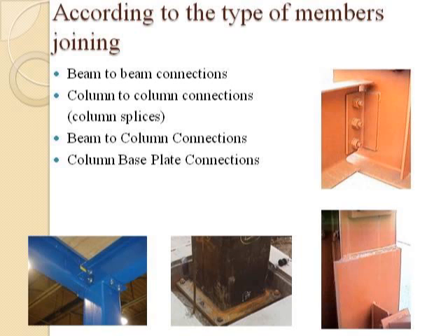Then we will have column to base plate connection. As we all know, the load is getting transferred from beam to column, then column to the foundation, as in the case of frame structures, RCC structures. So in steel structures also, the loads are transferred from beam to column, then column to the foundation. In between the foundation and column, we'll have a base plate. The base plate will carry all the loads from the column and transfer them to the foundation.